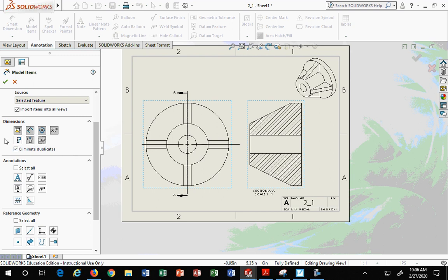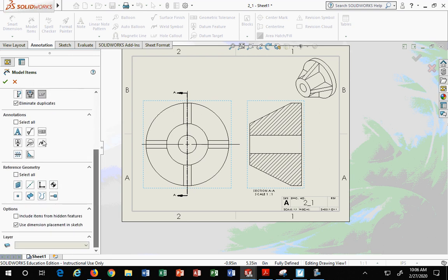The only thing it doesn't do well is that you cannot pick the whole callout information and the whole wizard profile; you have to toggle between the two. Personally, I prefer the whole callout. That's a personal choice. If you had any annotations included in your model, like finish quality, for those of you doing finishes for CNC, or any GD&T tolerance symbols, you can include all that, or any weld symbols for those of you in welding. Any reference geometry you want to include, everything is here. When you hit OK, it will literally,